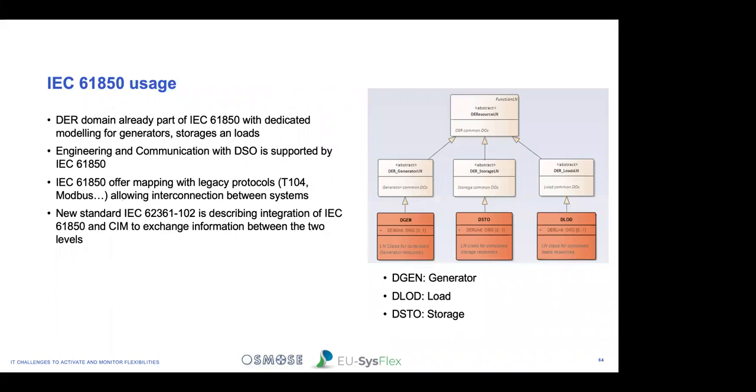And more precisely, how 61850 could be used in your projects. So first, the DER domain is already part of 61850, like what you can see on the right side. In 61850, we have defined different functions, which are called logical nodes in the standard. And as you can see, we already have implemented the different logical nodes related to generators, to load, and to storage.